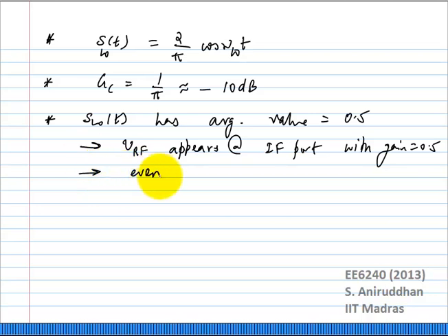So for example, let us say this is a direct conversion receiver, and your even order distortion has a component falling around baseband, around DC. Because this has a gain of 0.5 from the RF port to the output port, the even order distortion will go right through the mixer with a gain of 0.5, and this will cause DC offset problems or a time varying offset or whatever it could be. Causes IIP2 problems.